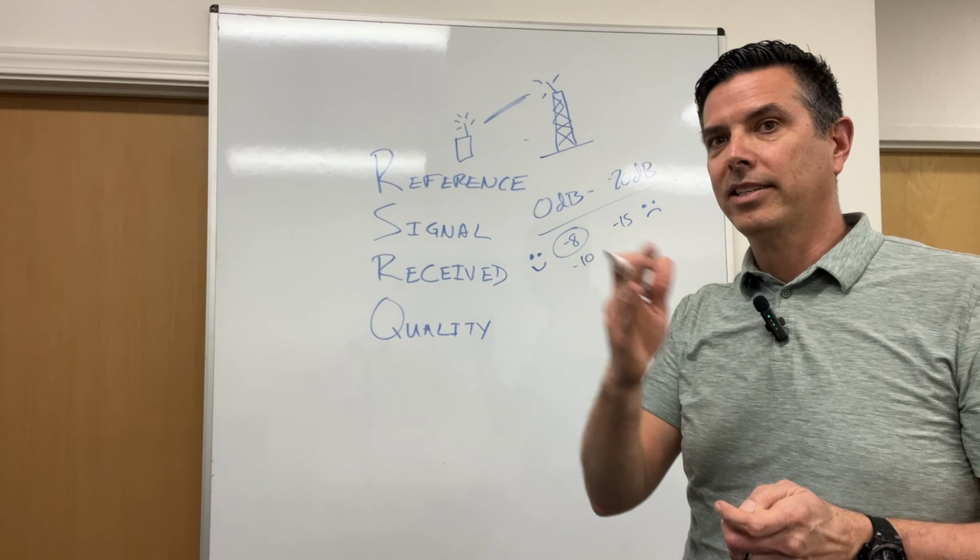When you're doing walk testing and you produce walk test maps, what you'll see a lot on a floor plan is a dominant PCI plot, right? Dominant PCI, meaning what is the most prevalent PCI on this floor? If you don't have a DAS and your service is poor, because you've got a lot of different cell sites, you're in a downtown area, you will see many different colors, and I'll show you an example of what that looks like. All the different channels coming in, it'll usually break down in the legend. All the different PCIs are percentage of data points.